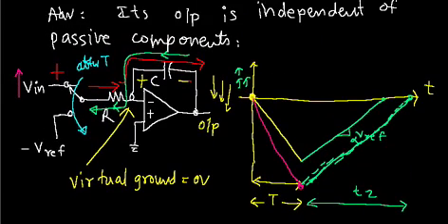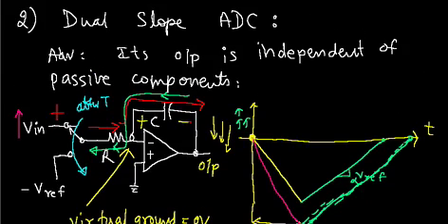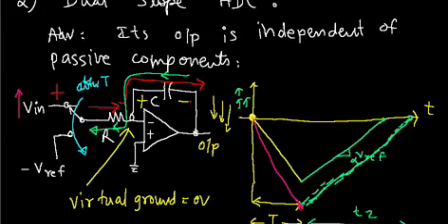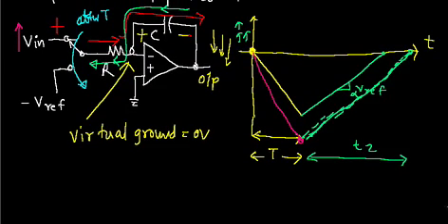And the first job of the A to D converter is done. Now what is that? Voltage to time conversion. Remember, the x axis is time. So if we change the analog input, time is changing. So the first job is over. Correct. So it can be used as an A to D converter, and we would like to check how the advantage is there. So for that, we have to write some equations.